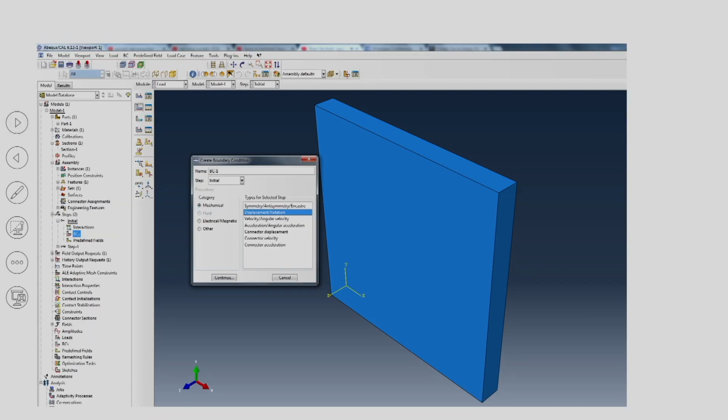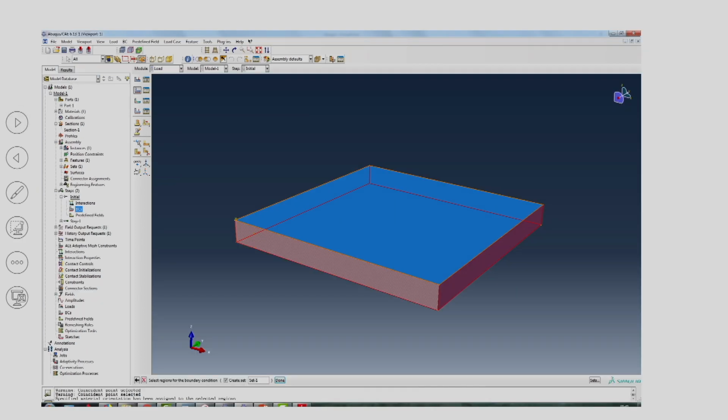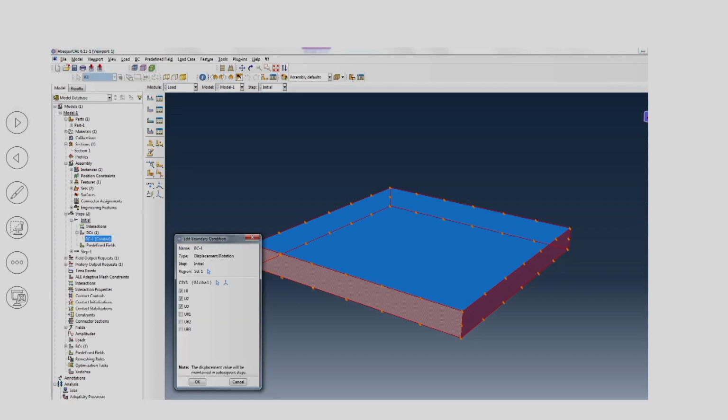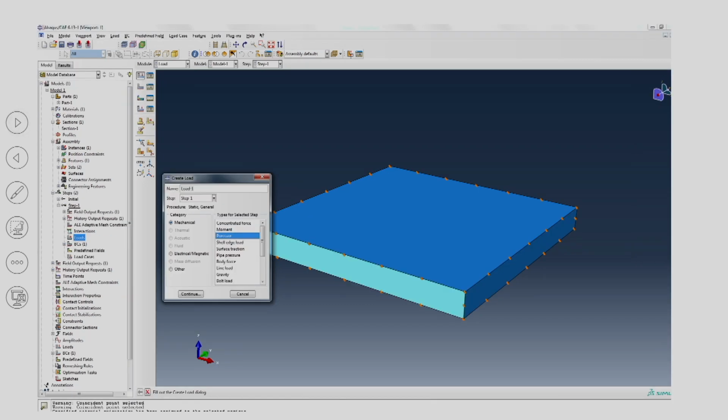Finally this part is ready, and then you have to go to the boundary condition. How do you apply a mechanical boundary condition, an electrical boundary condition or another type? From this section one can decide and apply the boundaries. You see that U1, U2, U3 all zero means clamped. They put it as BC1, BC2 and so on, and then you have to apply the pressure load.